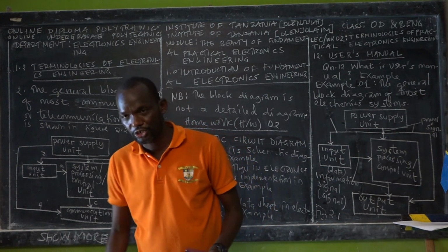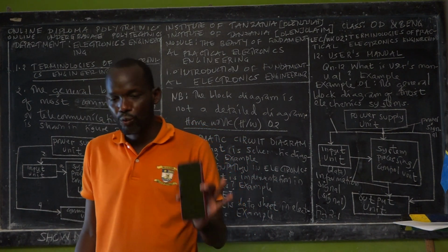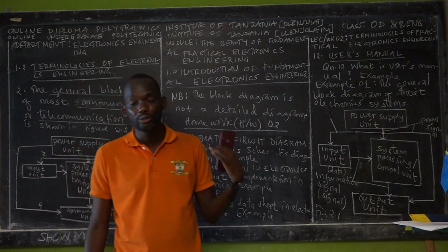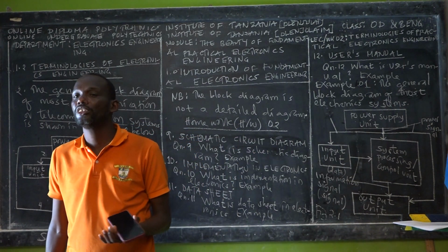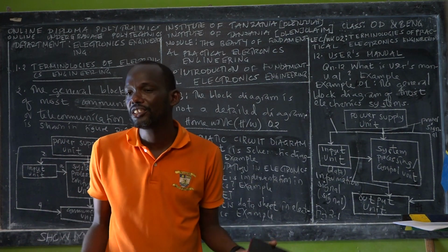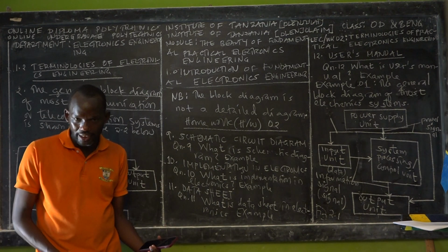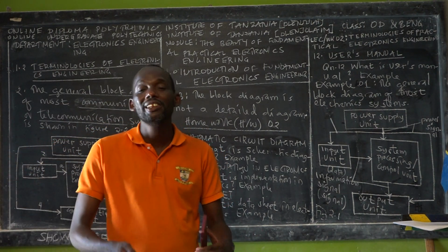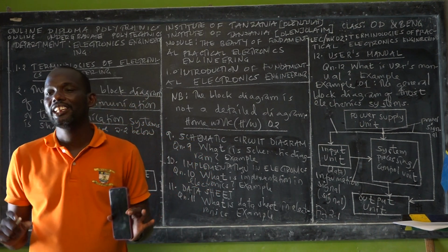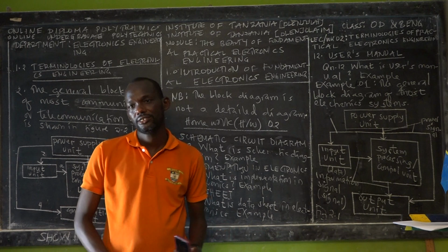The USB cable provides 5 volts, but once you read the specifications, the voltage stored in the battery of most mobile phones is 3.8 volts. So there should be a circuit to lower the voltage from 5 volts to 3.8 volts.